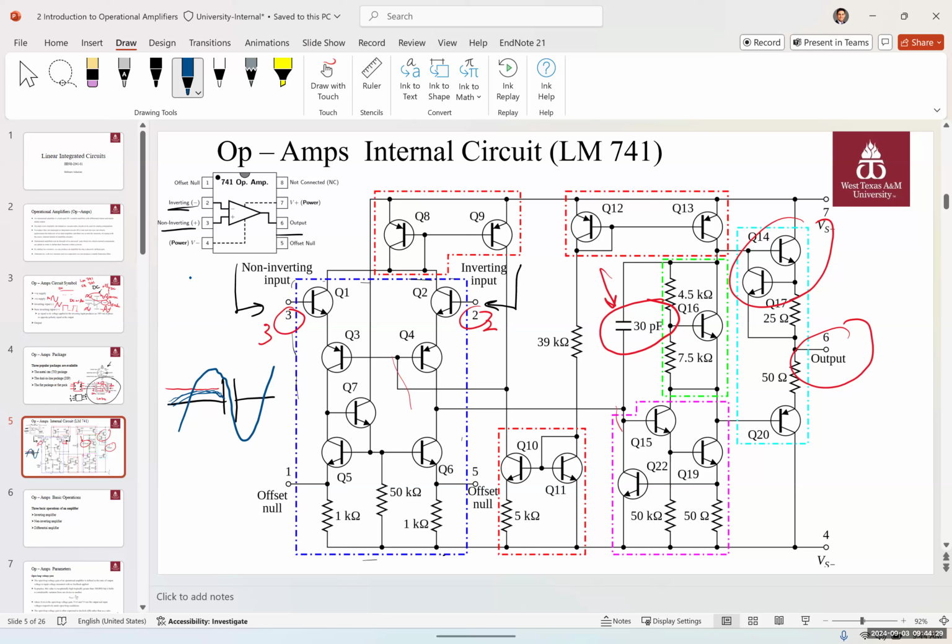Therefore, a coupling capacitor, which is a large capacitor, sometimes if you have a low frequency, it's going to cut off and shut down your amplifier. So these amplifiers usually have a limitation, which is called the cutoff frequencies, and I'll explain more about that. But the cutoff frequencies are determined by the transistors themselves, because the transistor has metal terminals. Those metal terminals act like a capacitor. If you put two metal plates and an insulator between them, it's going to act like a capacitor.